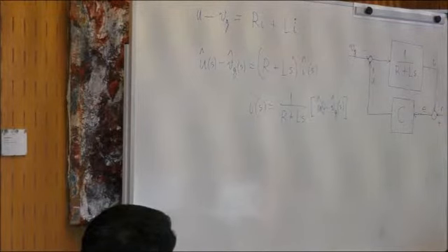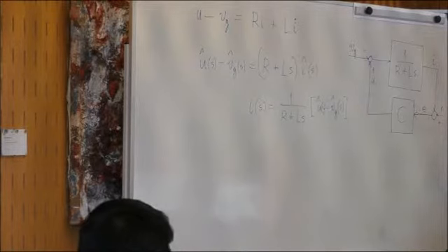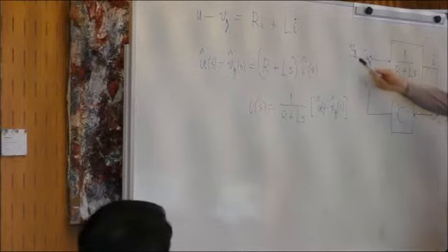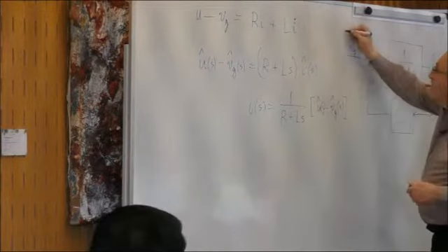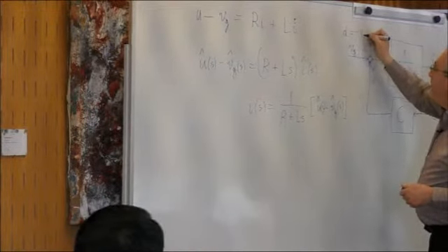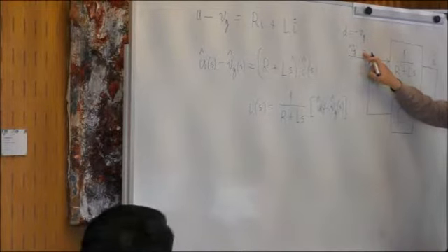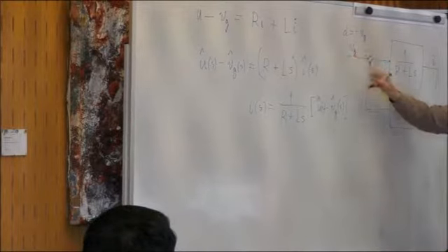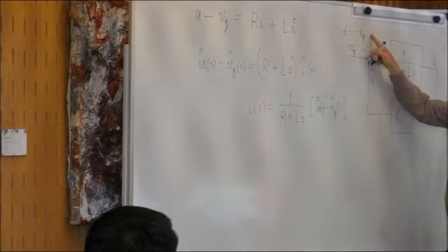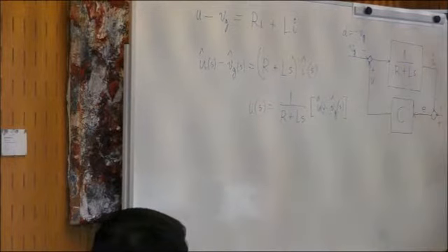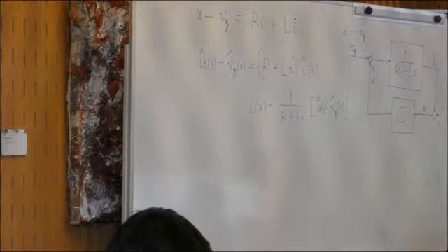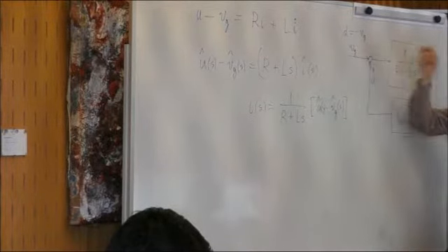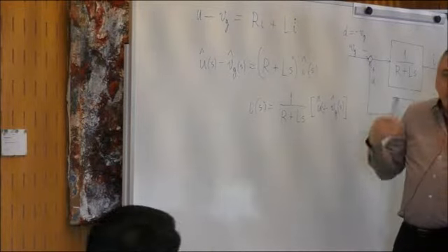And you want to follow a reference signal which is sinusoidal with frequency equal to the frequency of the grid. And you have the disturbance signal, so you notice that D is equal to minus Vg, because you have this minus sign here. So if I would change it to plus and write D, then the disturbance would be equal to minus Vg, right? So if I want to make it like the previous picture, then this is my disturbance, minus Vg. So the grid voltage is my disturbance,